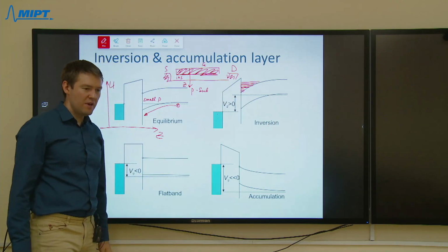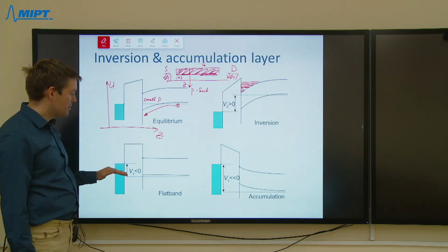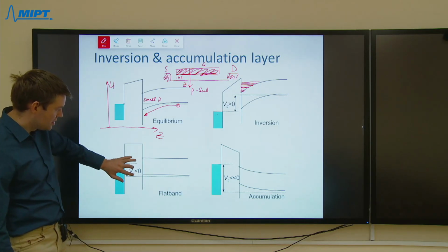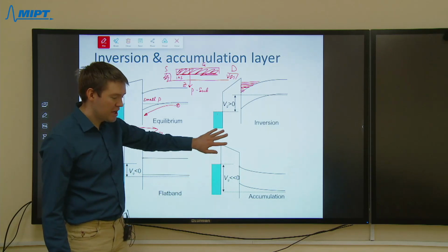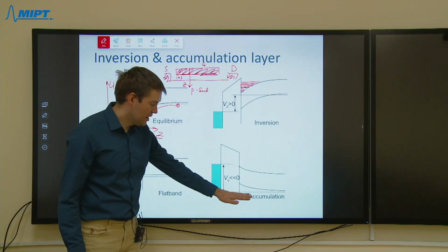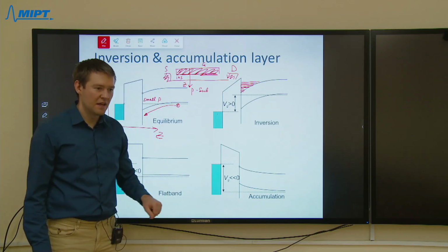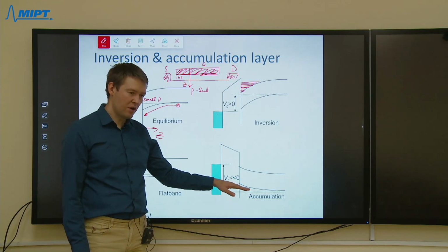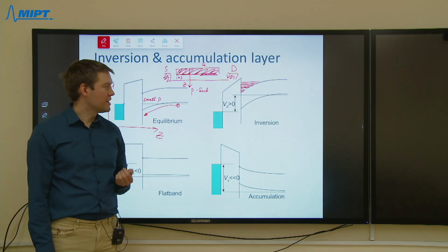Of course, there can be other regimes of gate voltage, like we can apply negative gate voltage, and we can attract holes to the metal surface. And we can apply large negative voltage to attract a large number of holes near the metal surface. And this would increase the hole type conductivity and reduce the electron type conductivity.